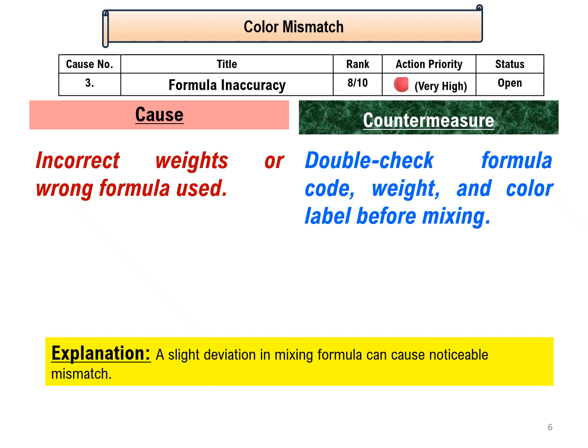Number three, probable reason could be formula inaccuracy. That is, incorrect weights or wrong formula used. A slight deviation in a mixing formula can cause noticeable mismatch. Therefore, double-check formula codes, weight, and color label before mixing.